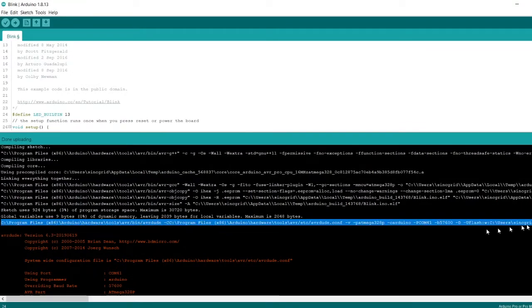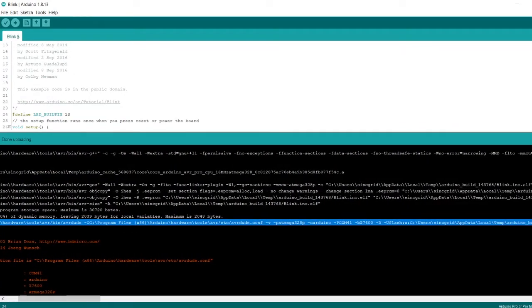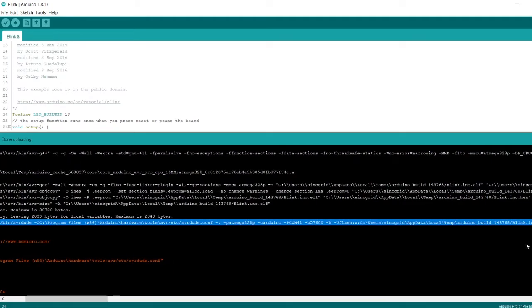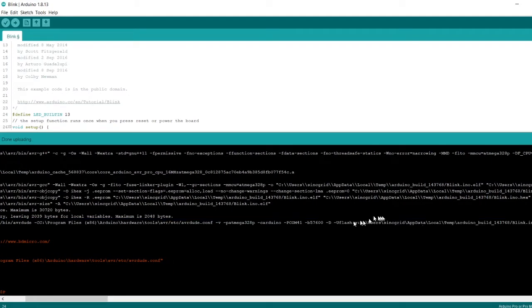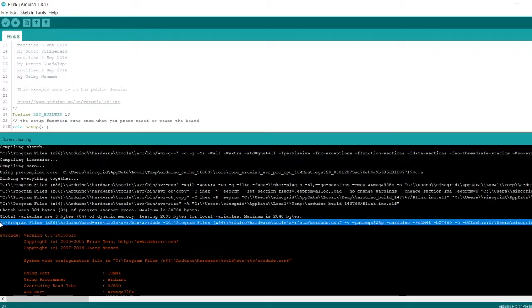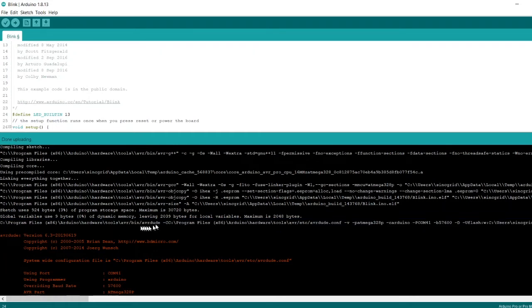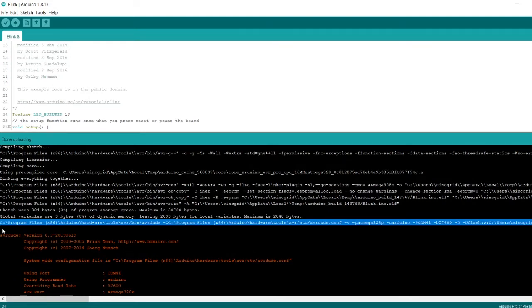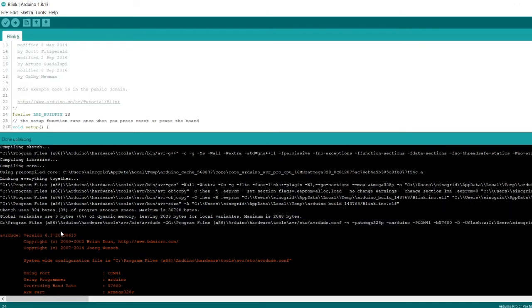You can just push any example code since this Pro Mini bootloader is there. Then you can see that this line is basically specifying what path I am following in this environment. So I'm using the predefined, pre-installed avrdude with the Arduino IDE, and I'm just copy and pasting only this line. Other than that, I'm not utilizing anything from the Arduino IDE side. I'm just utilizing its programming mechanism to utilize the bootloader and transfer the hex code from the